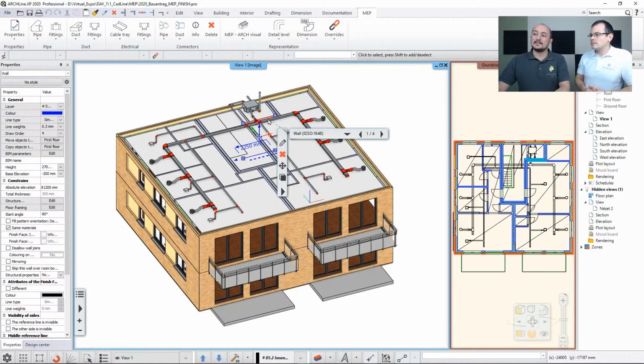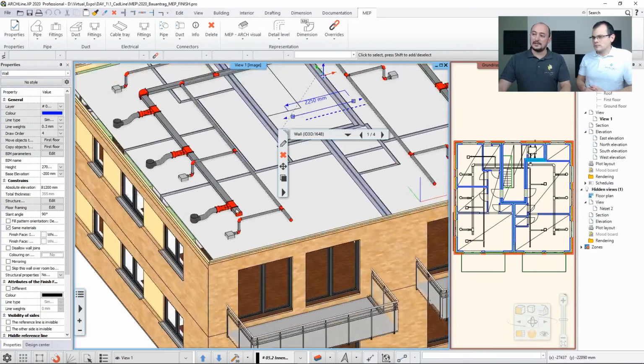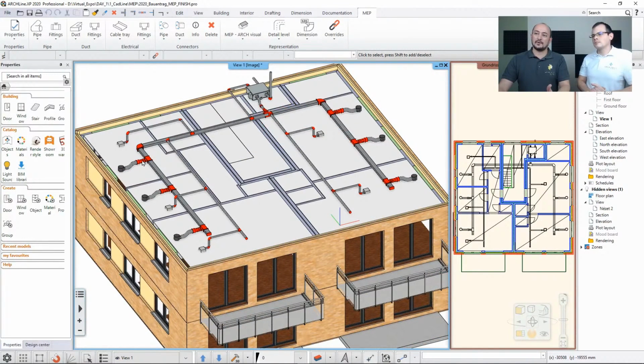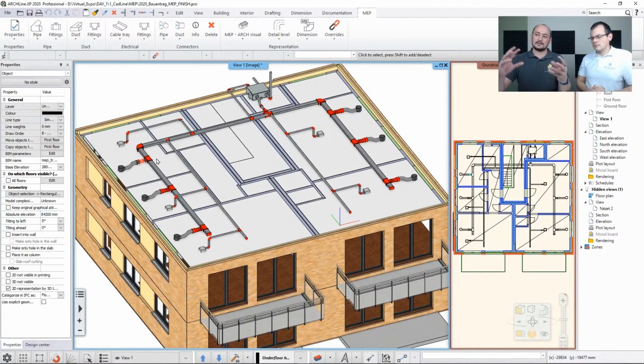And tools. Well, actually, it is similar to drawing walls. You actually draw the pipe system. You can change the length of the pipes. You can change the endings. You can always attach new branches to these systems, and the software will handle them as one single system. So when you erase something, it won't just break up here, but it will make it a whole pipe again, so it will handle it as one real MEP system, should that be any sort of duct or fitting or anything else like electrical.